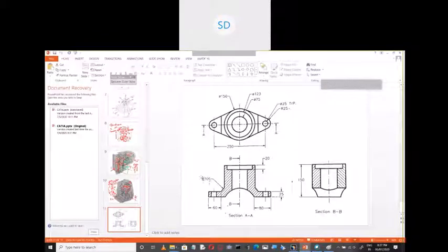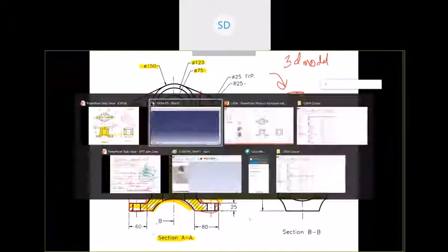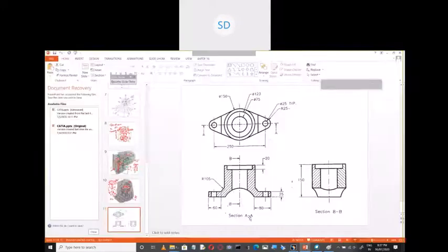You can just observe it. This is the 105 outer radius. Then these are parallel. Thickness is how much? It is 25. That means the inner radius is how much? It is 80. Now as they have not specified where it is going to intersect, let us take it from its quadrant point itself.